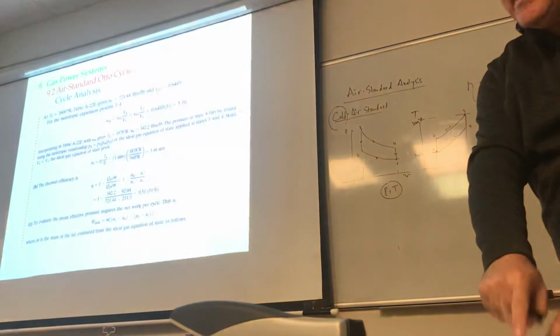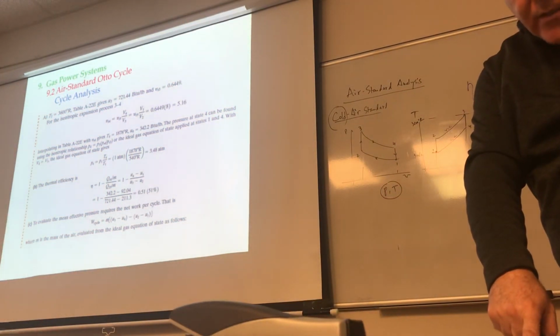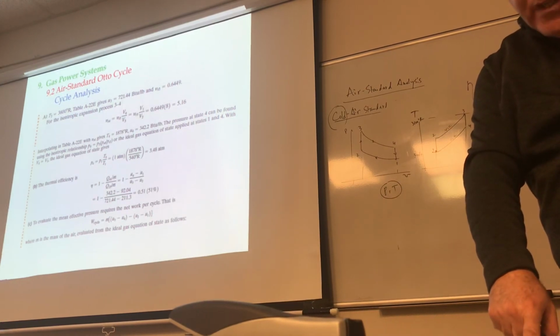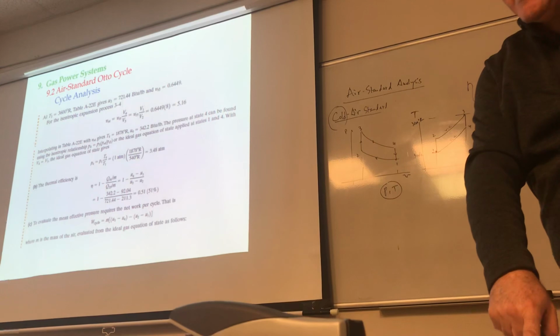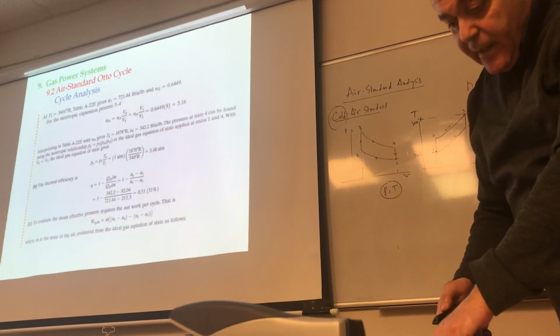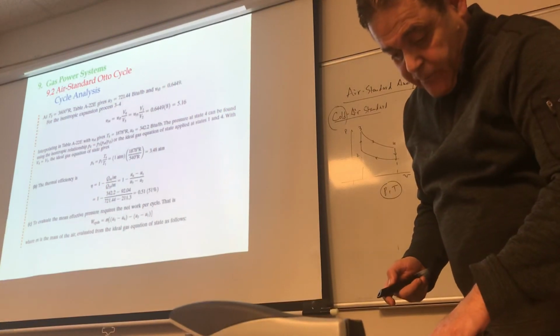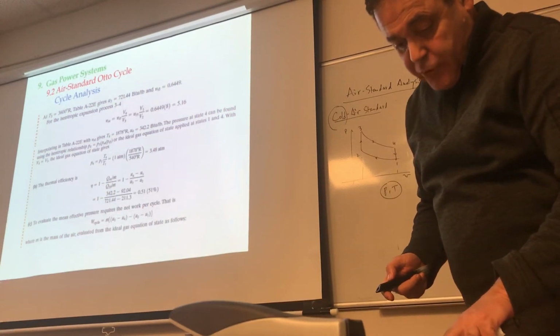Then what do you do after you compute the VR? You try to locate it on the table. See? And I look on page 904, it's not there, right? Because the maximum value of VR there is what? 3.176. So I probably need to go to the previous page. And 5.16 will be between what and what? Which temperature and which temperature?